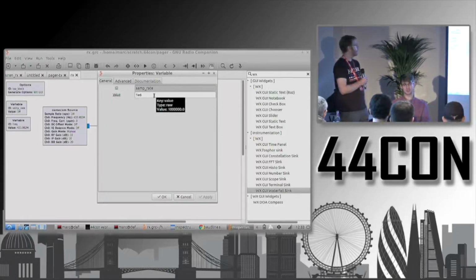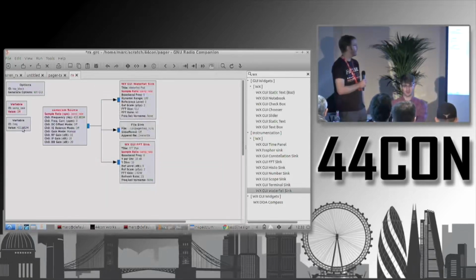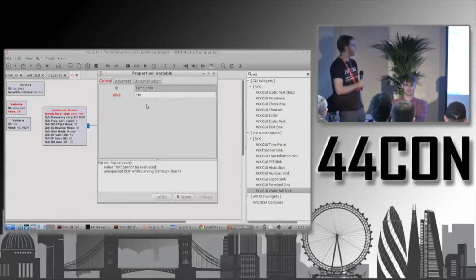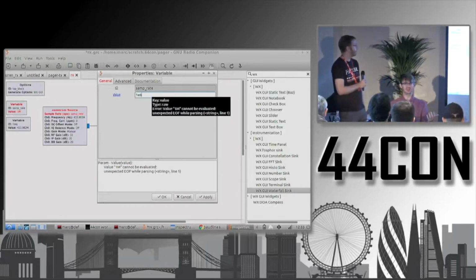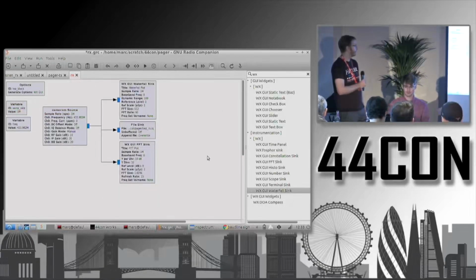This is actually kind of confusing. GNU Radio will render it with K, M, or G to represent 1,000, million, or billion. However, if you put M in here, it doesn't process it. You have to basically list the variable names as scientific notation. However, it will display them using alphanumeric letters. So use E for 10 to the power, and then what follows E is the power.